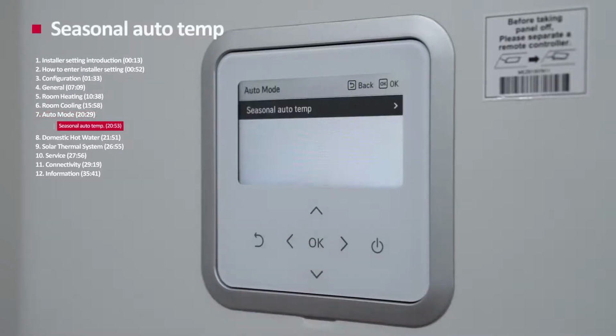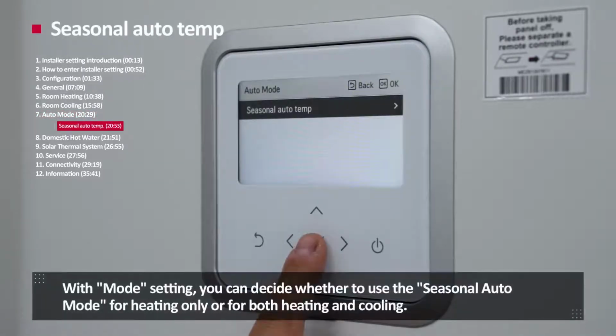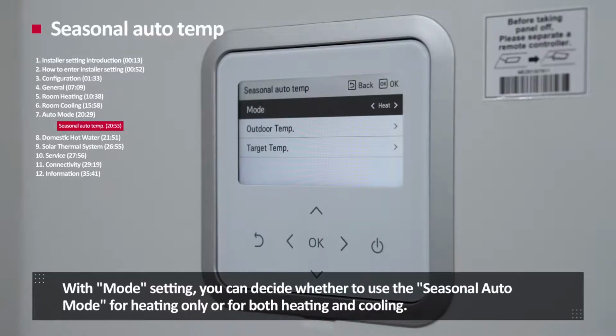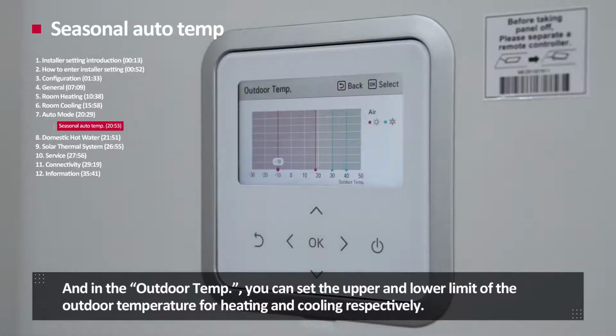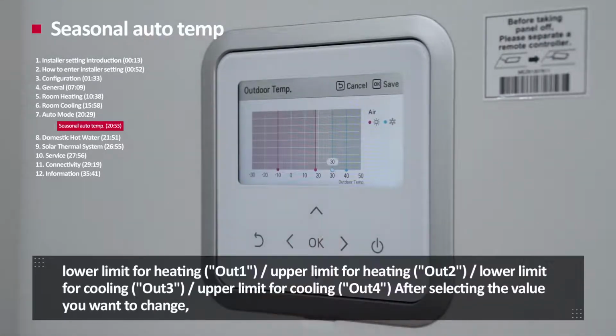Seasonal auto temperature. With mode setting, you can decide whether to use seasonal auto mode for heating only or for both heating and cooling. And in the outdoor temperature, you can set the upper and lower limit of the outdoor temperature for heating and cooling respectively. Lower limit for heating, out 1. Upper limit for heating, out 2. Lower limit for cooling, out 3. Upper limit for cooling, out 4.